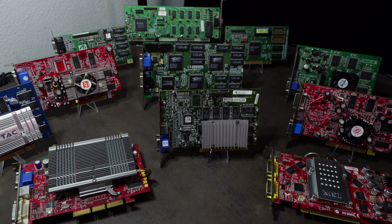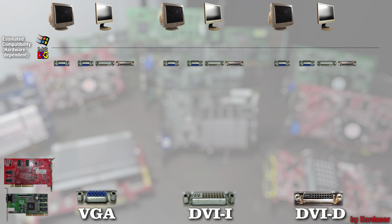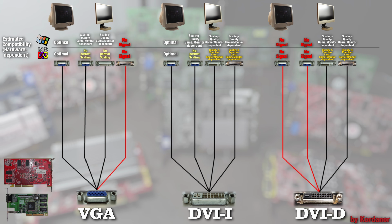So when choosing a graphics card, you need to make sure that the card as well as the monitor can both either process analog or digital signals. The plug itself only plays a role in so far that it can exclude one or the other option. If you got an analog signal from a DVI connector, you can easily connect that to a VGA port of a monitor using the right adapter.